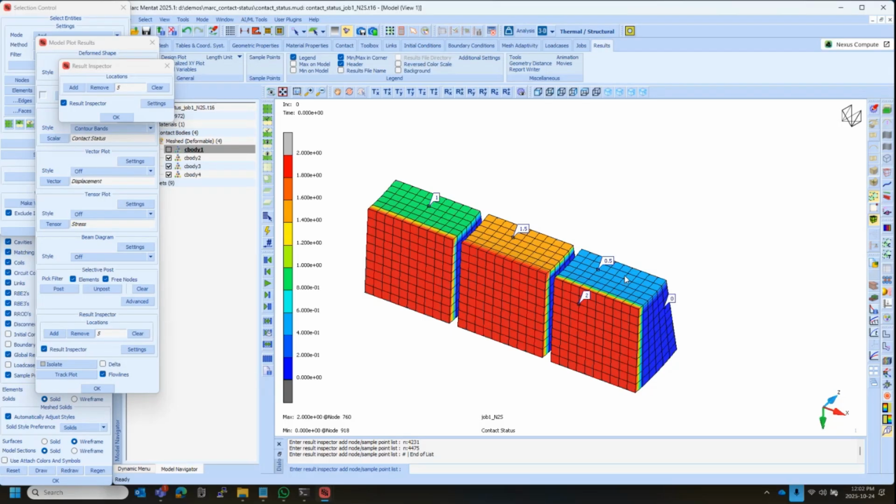For thermal analysis specifically, if there's a small gap between 2 parts, heat can already be transferred between them through convection and radiation and so on. The equation and the method to do that is a lot simpler than trying to do radiation for a complex structure. So for this, 0.5 means it's close to in contact, but it's not yet in contact. So heat transfer takes place. Value of 2 is used for cyclic symmetry.